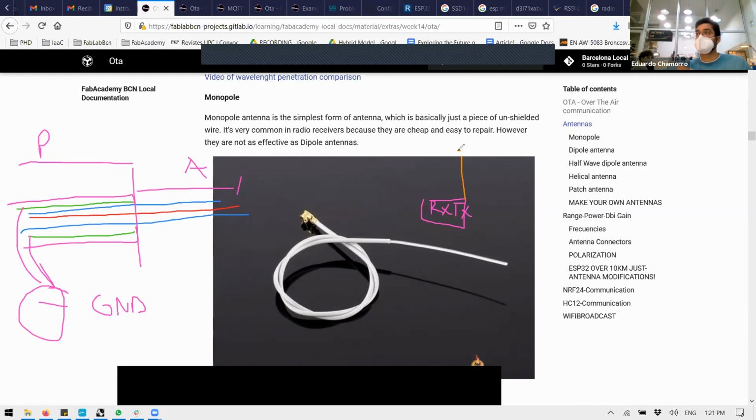No, in that case, you need to have all the antenna protected so it doesn't get any electromagnetic interference from any other devices until you get to the correct location, and you just show your active part of the antenna. First case. Second case, in antenna design, the length of the passive has an influence on the sensitivity.